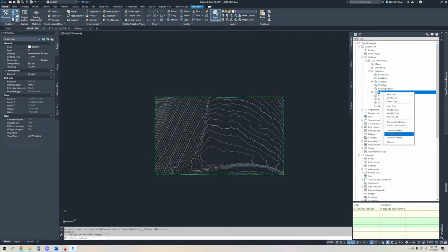We bring those two gradings together, and we create a brand new surface. With that brand new surface, we can go to this option here, which in my case, I only have one surface, so it's not an option for me. But I can go to paste surface, and I can paste both of those two surfaces into my brand new third composite surface to create one final combined surface.